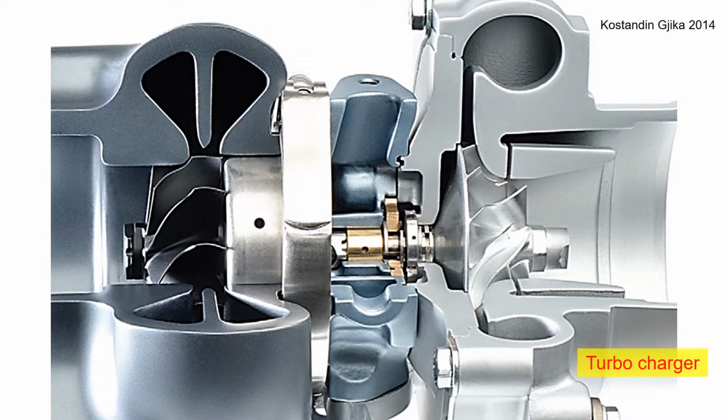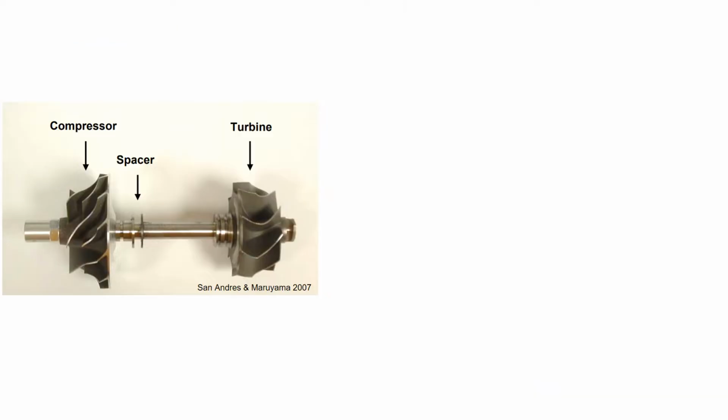So understanding the energy source is important if you want to reduce the vibration, but your machine is operating at a high speed, such as turbochargers in automotive. In the early design stage, it is important to perform impact tests and compare the test result to the rotor dynamic model. Here is how the process flows.